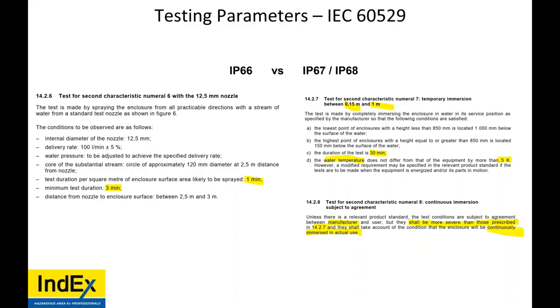When an enclosure is rated IP67 and has a cutout made for a cable entry or for indicator installation, how to maintain the IP, how does the requirement vary if installed indoors or outdoors? Well, when there's no threads, that can only be guaranteed to be IP54 with an IP washer. If there is no threading and it's just an open hole, you shall always use an IP washer.